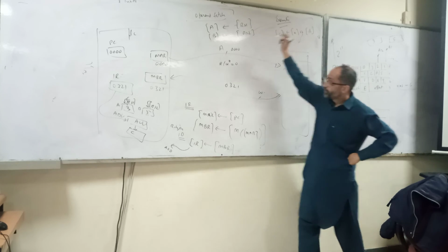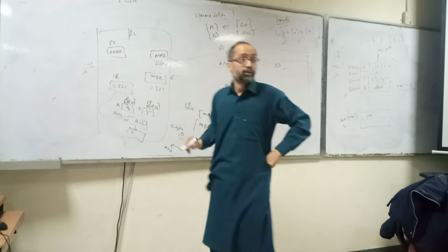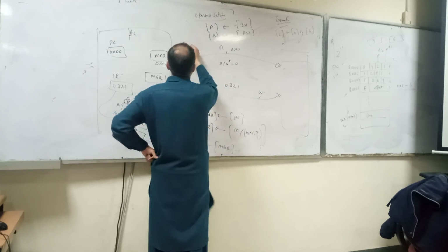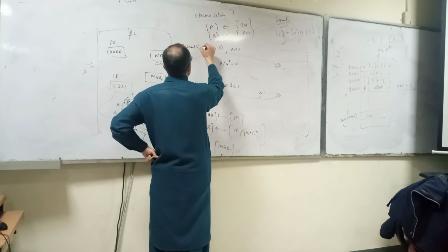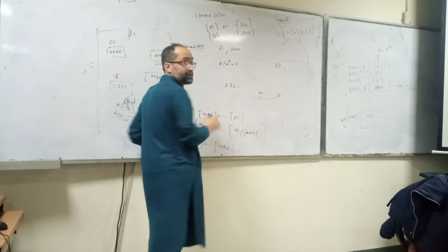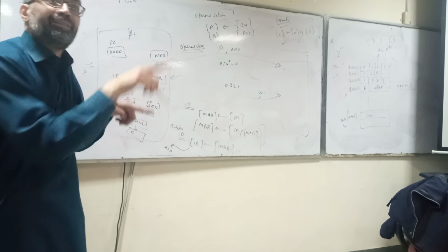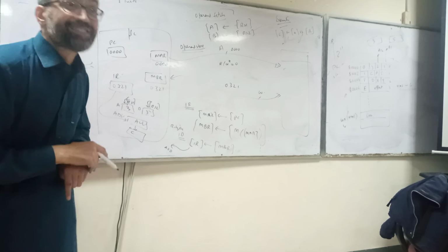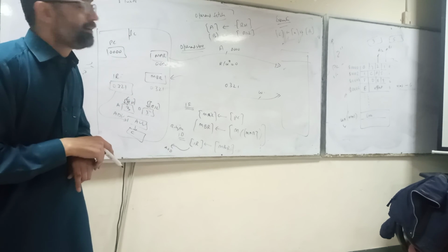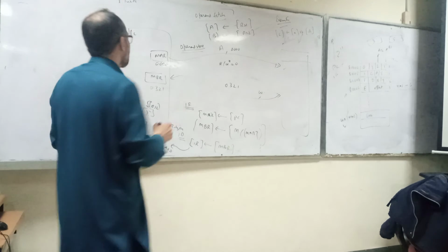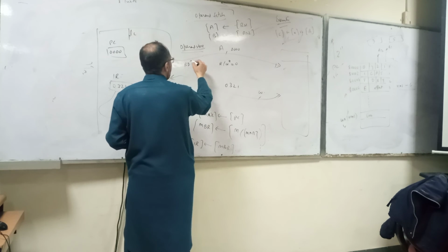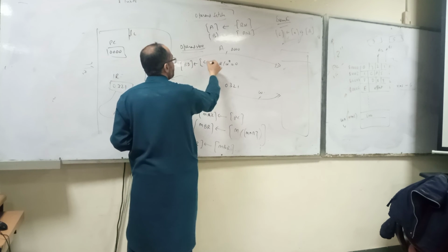Then after execution, another stage is the operand store phase. In the operand store phase, the contents of C are written into the external register, the RD field. So RD is updated with the contents of C.